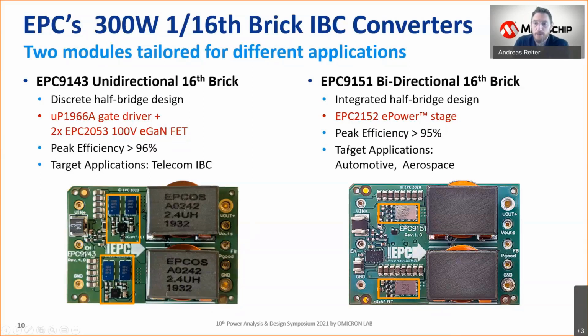When we compare the complete efficiency between the two almost identical designs, we see that the discrete design is overall still roughly 1% more efficient than the integrated one. However, having an integrated device leaves us more board space. Board space means we can put more input capacitance in there, and eventually we could even squeeze the size of the board a little bit further.